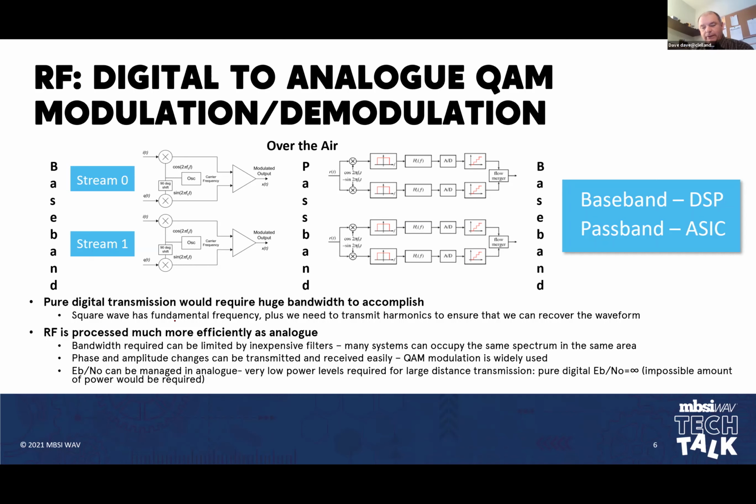would have not only the fundamental frequency of the square wave, but also the corners of a square wave. So if I have a square wave like this, at these corners, I am generating intermods like crazy. At that point, I will generate first, third, fifth, seventh, ninth order intermods. All kinds of extra frequencies get generated as the carrier turns on and as it turns back off again. So pure digital over the air is a very inefficient way to transmit and receive the data.